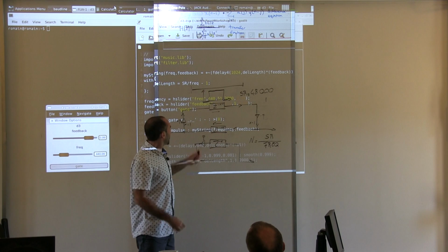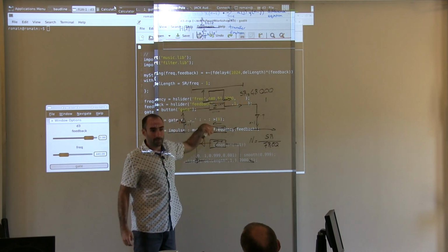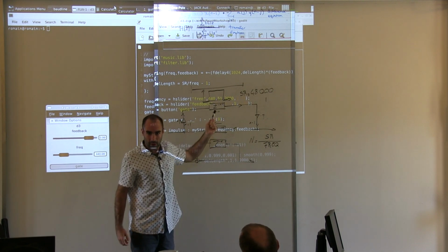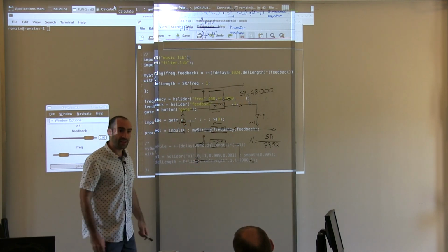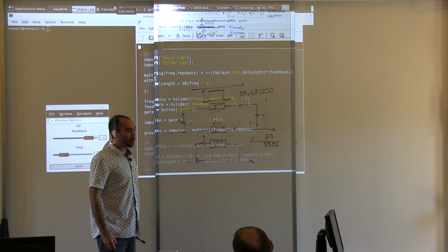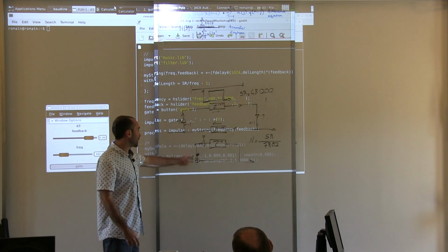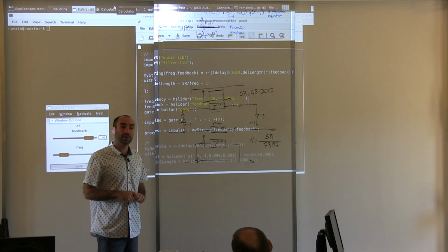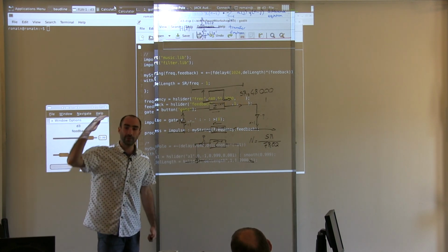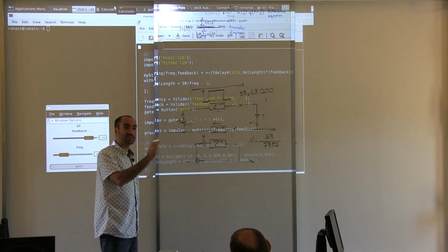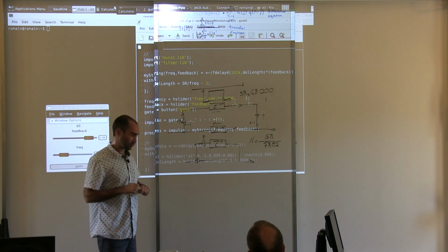So our bridge and our nut here are frequency dependent, right? So an improvement that we can make to our little system is that instead of removing the energy linearly across the spectrum of the sound by just doing a multiply, we could actually apply a low-pass filter in here to remove high frequencies first and lower frequencies last, right? Does that make sense? Okay.